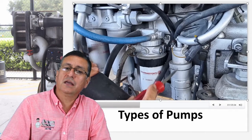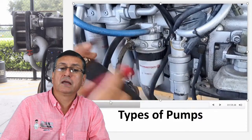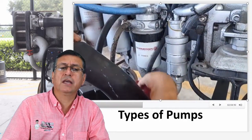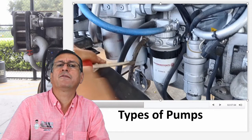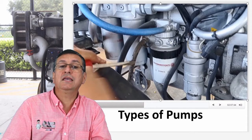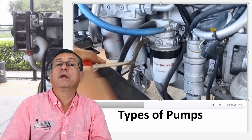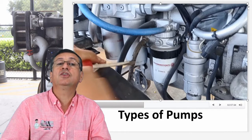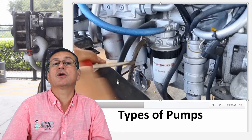All right, this is the fuel injection pump, electronic fuel injection pump, that's the input, and this is the output, correct? That's the signal coming from the computer. This is the output, and the output enters the filter, the secondary filter. Okay, my friends? Because this is high pressure, it's 3000 psi or higher. This filter has a return on top into the tank. When the engine is in idle, a lot of fuel returns into the tank. When the engine is at wide open throttle, high RPMs, less fuel returns into the tank.